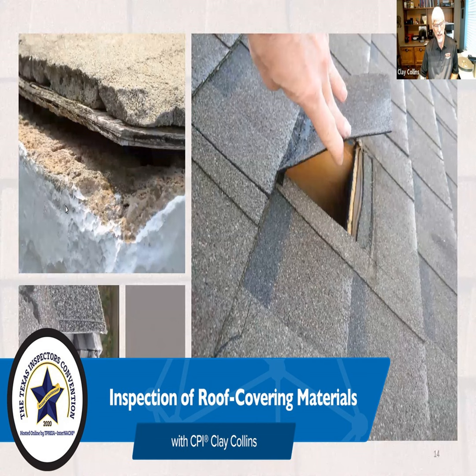And don't forget that if you can't go on the roof, you're not excused from using the ladder to view it from the eave. You may not have to actually walk on the roof, but even if you don't walk on the roof, if you can reach it with a one-story ladder, you need to put the ladder against there. And something else you should do, since we're talking about a photograph here, is put your hand, put something there, so that your photograph shows that you actually reached that roof line.